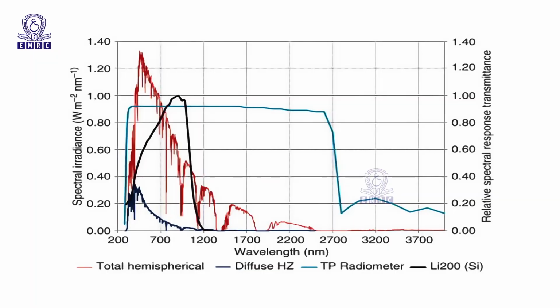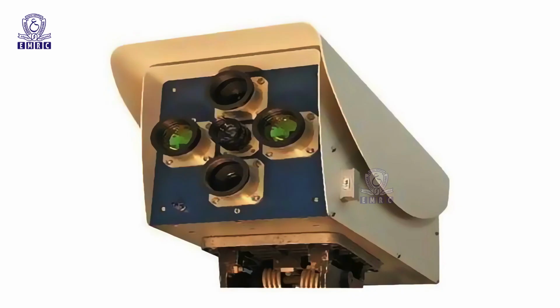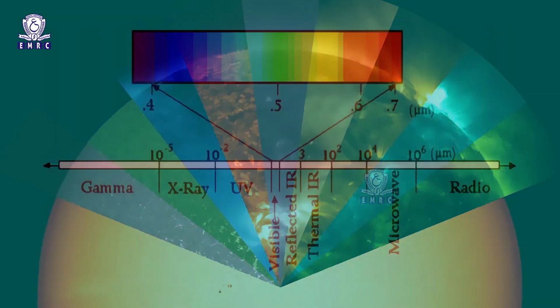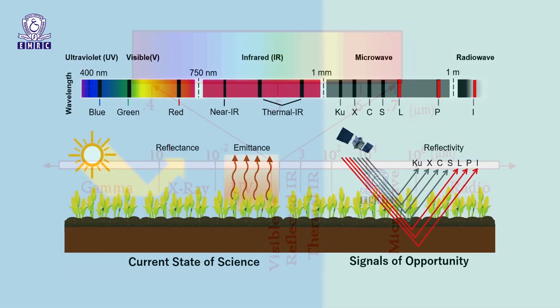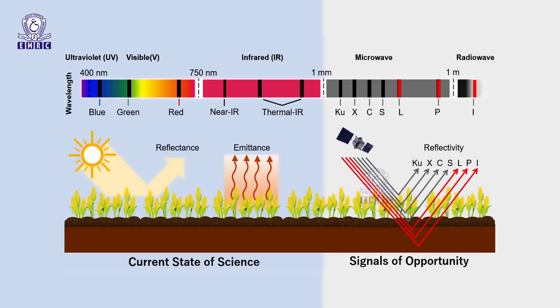Detectors for radiometers have been devised to measure wavelengths from 0.4 to 14 micrometers. Although some radiometers can detect this entire range of wavelengths, most only measure selected wavebands in this range. Radiometers that measure more than one waveband are called multispectral radiometers. For this type of radiometer, the light must be separated into discrete wavebands so that multiple waveband or multi-channel readings can be taken. This separation can be done using filters, prisms or other sophisticated techniques.